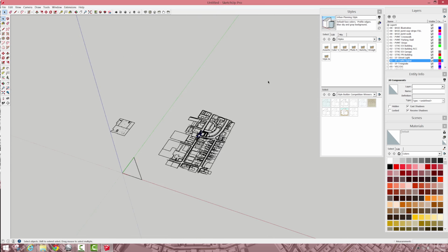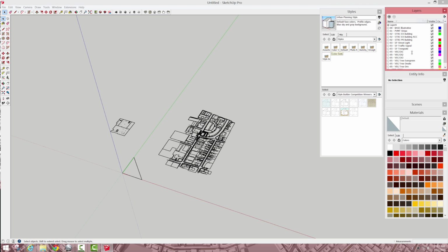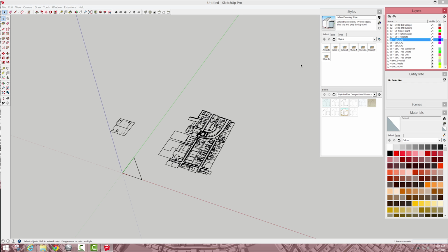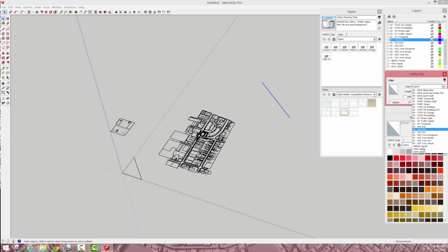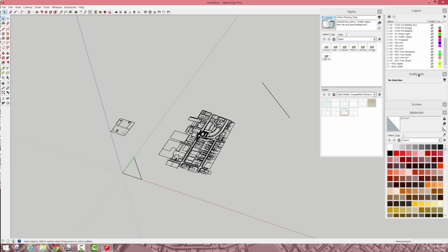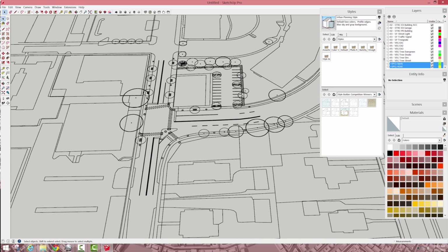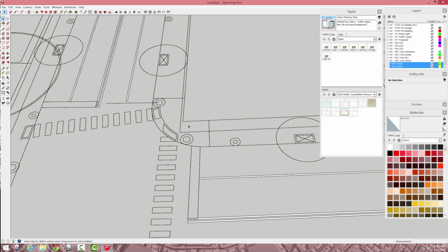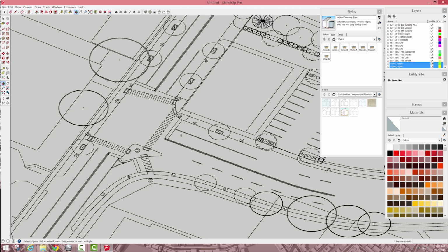So the other thing I'm gonna do is purge all unused and just double check that I have everything I need. Oops, I need one of those layers. The B poly layer we use as kind of our like no plot. So like the right-of-way and the B poly layers are both kind of no plot layers, but we like to keep them, they're good references. So some of the information that's inside this line work, like what'll be inside our blocks, will go to no plot, but we use them as source and reference.